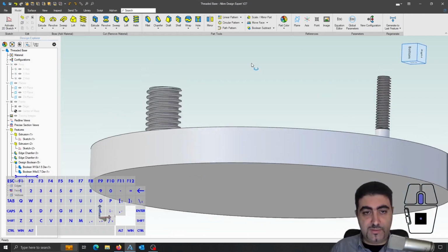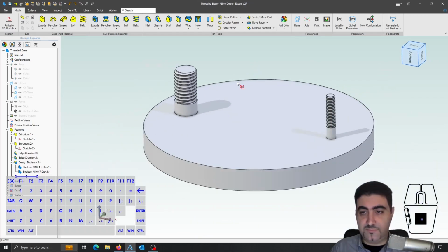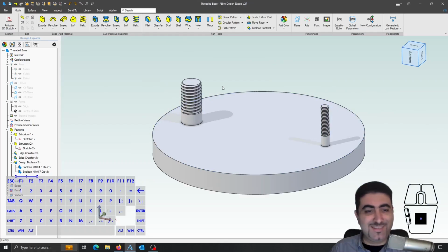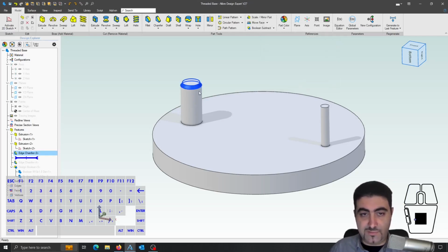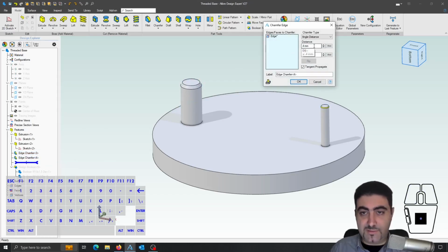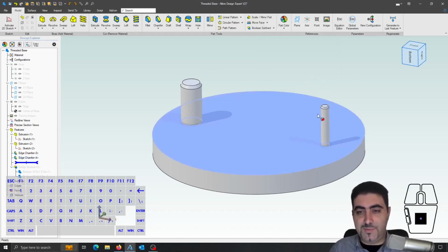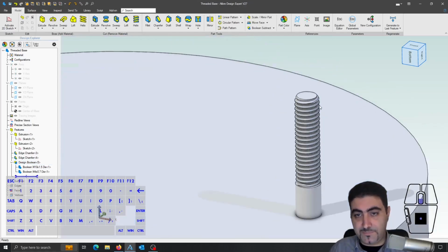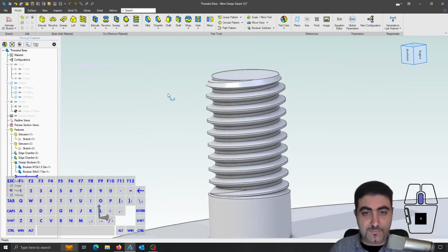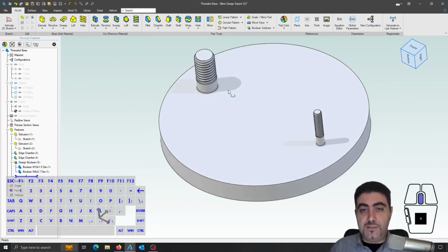Right? Well, the chamfers didn't come out very nice. Yeah, I don't like them. Let's make them bigger. You know what? Let's give this 1.5. Cool. Let's make this 0.7. So the thread pitch. I think I remember I did this in the other video. Yeah, that's a lot better. Yeah, significantly better.